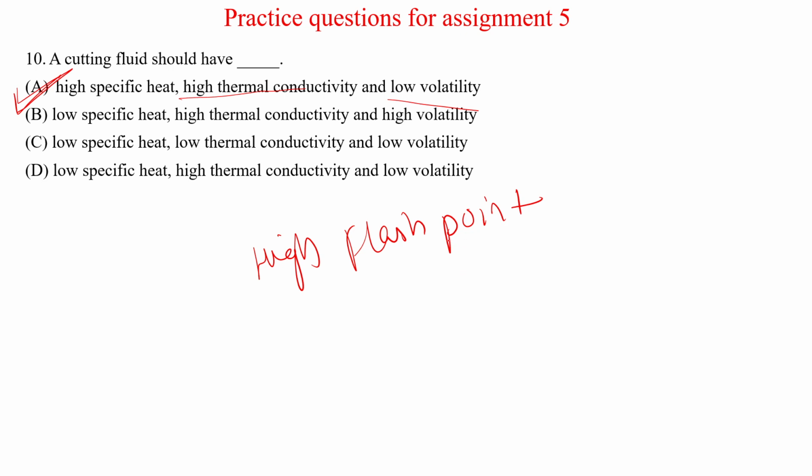Flash point is that particular temperature at which the cutting fluid burns. So if it has a very high flash point, then you will require a very high temperature to burn it, and we want that only. It should not burn from a small spark or temperature. So it should have a very high specific heat, very high conductivity, low volatility and high flash point.